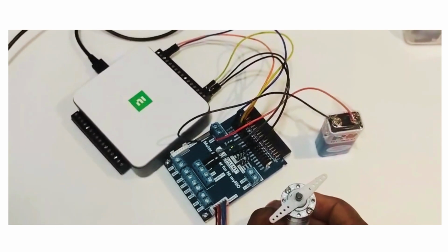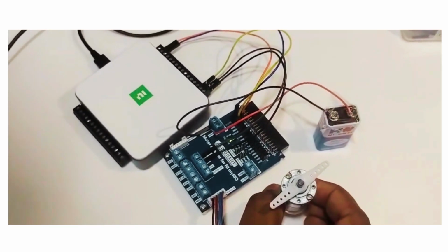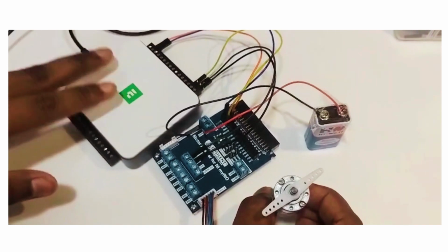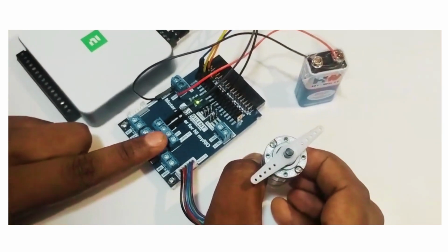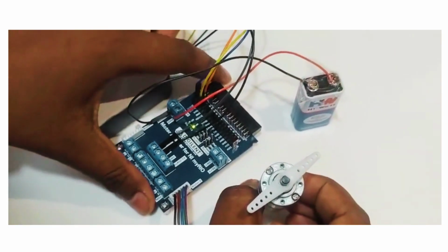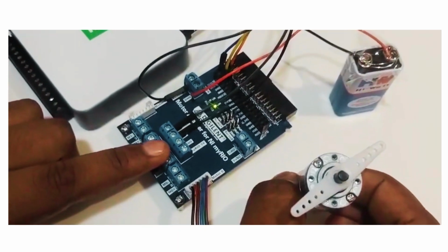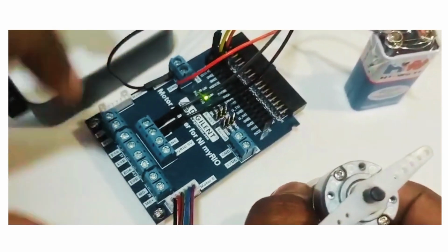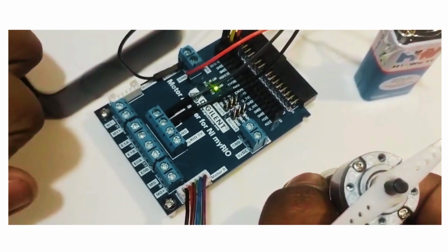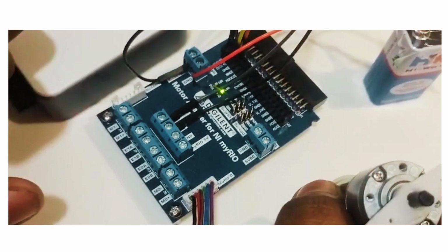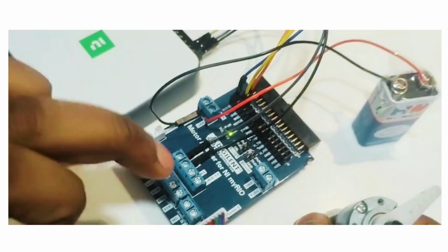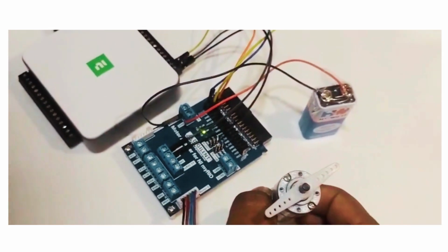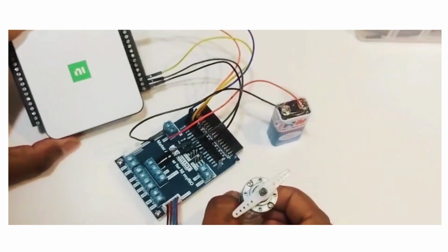For hardware demonstration, that's how to control a DC motor using NI USB DAQ 6001, and this is our H-bridge controller board. And this H-bridge control board has 4 power MOSFETs, and it is controlling the DC motor speed, torque, as well as the direction, and provides the PWM signal from H-bridge to the DC motor. And this is our NI USB DAQ.